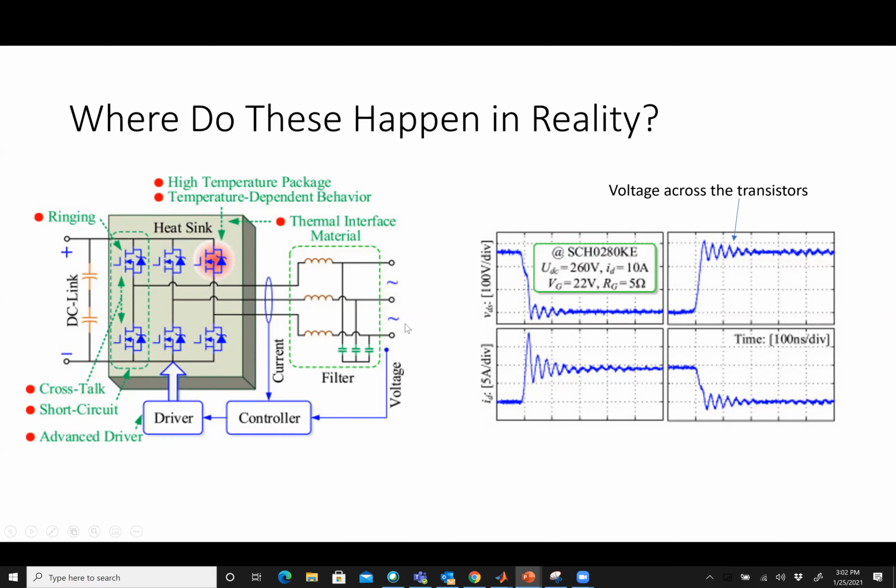All right, so if I look carefully, in some of these cases, if I look at the voltage across one of these devices, what I'll see is that the voltage will look something like this, which is an underdamped second order type of response, okay? These happen all the time. These happen in digital circuits. This guy here is basically a form of a digital circuit, all right?